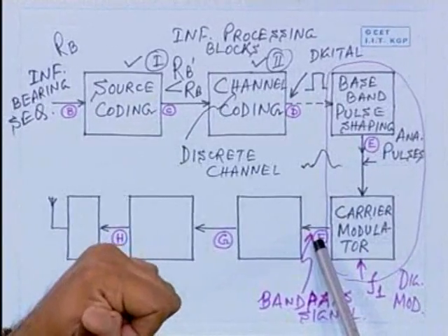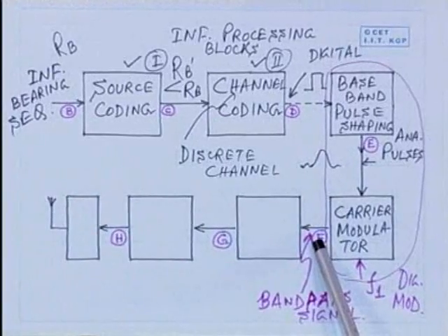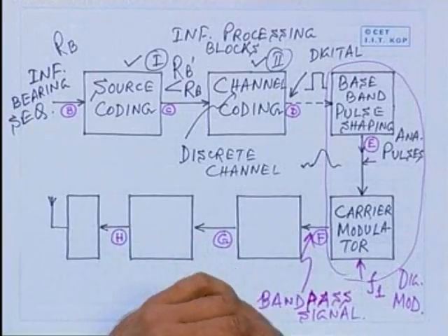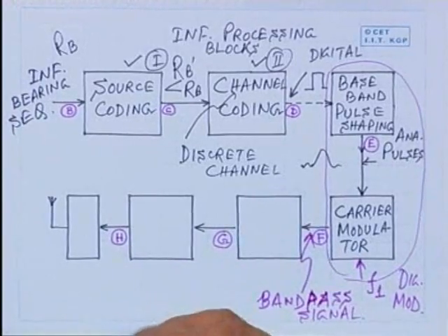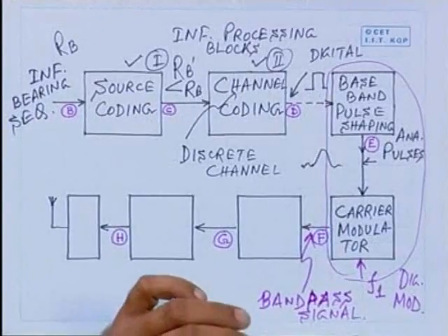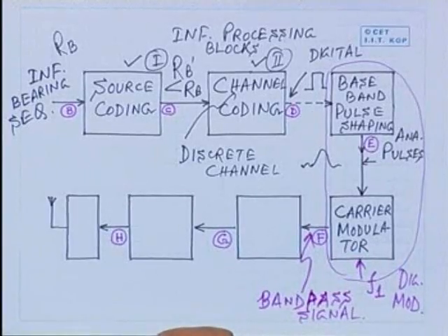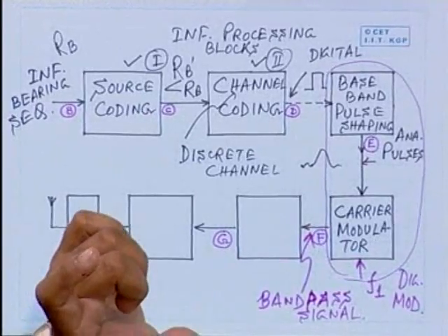A thumb rule is that within 10% of the value of the center frequency, we say that modulation is a narrow band modulation scheme. There is a counterpart which is gradually becoming very popular now, known as wideband modulation scheme, for which the bandwidth after modulation is quite appreciable, maybe around 10% or even more in some cases compared to the modulating carrier. Our discussion in the course will be wholly on narrowband modulation schemes.